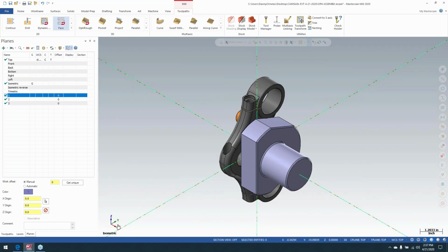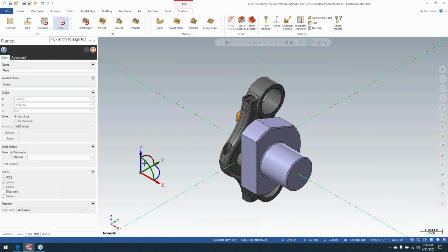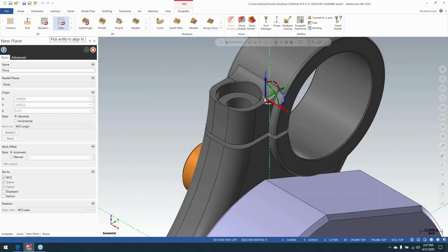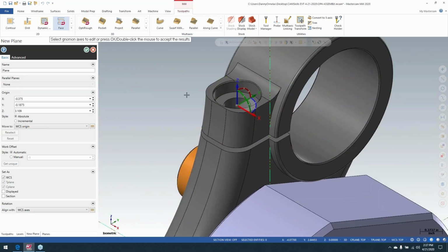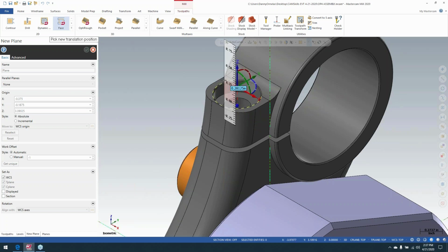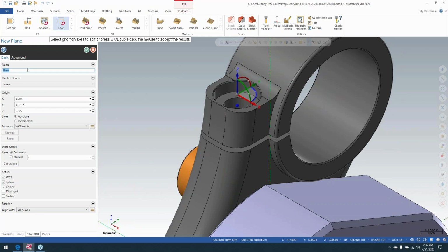And the same thing here, I'm going to go ahead and click my icon. I want to pick the center of this guy. This is already all machined from the previous operations. And then as far as setting my Z, I'm going to go ahead and just pick somewhere up here on top, right? Call him spot -1. I'm going to create a manual work offset, call him 0 for G54 again. Select OK to that.